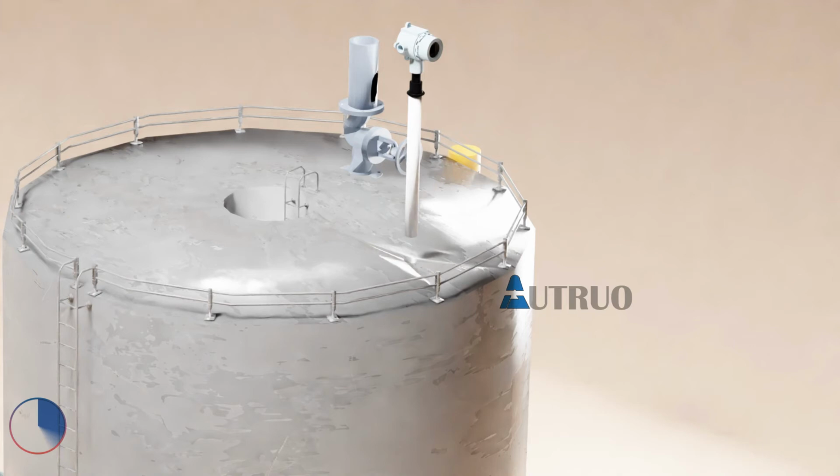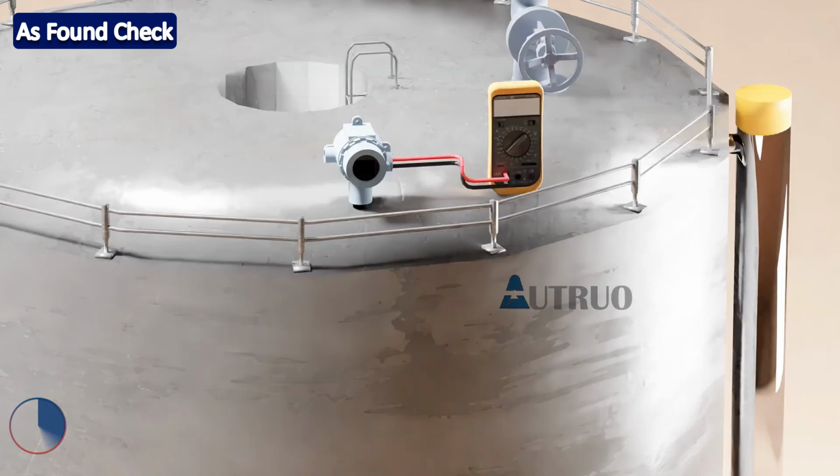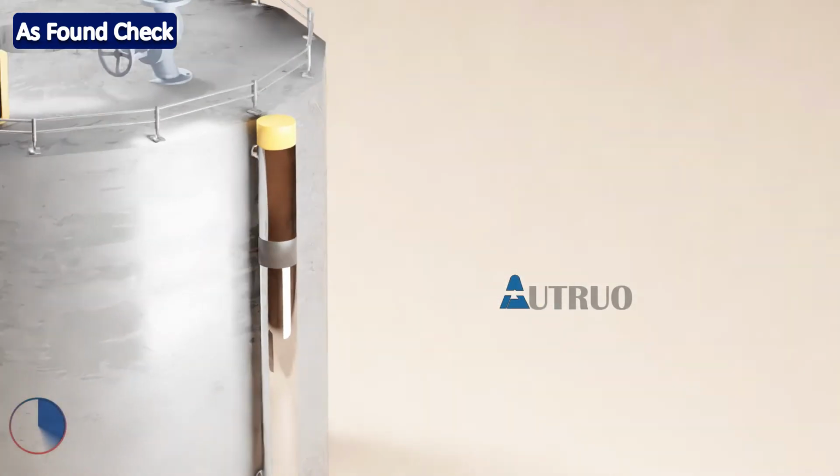With this, we will be able to understand the reason why the pump is not cutting off. We will connect a 24 volts power source to our level instrument, and a suitable ammeter will be used to measure the output signals of the transmitter. In this case, we are using a digital multimeter. We will empty our tank and have a look at our multimeter.